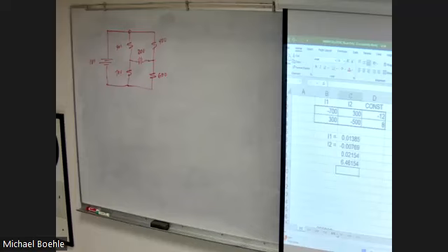So if I choose one of them as a reference node, that will not be known. And because there's a voltage source between that reference node and another node, that will be another known voltage. So how many unknowns did I end up with? Two. I only need how many equations then? Well, I shouldn't say that. It's not two equations, two unknowns. Right? It'll come.